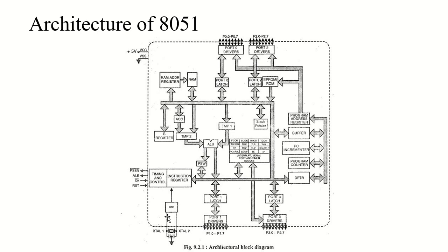The pins XTAL1 and XTAL2 are provided to connect the resonating network comprising the crystal and the capacitor to form an oscillator, and normally a quartz crystal is used, right? The capacitors are used to stabilize the network.